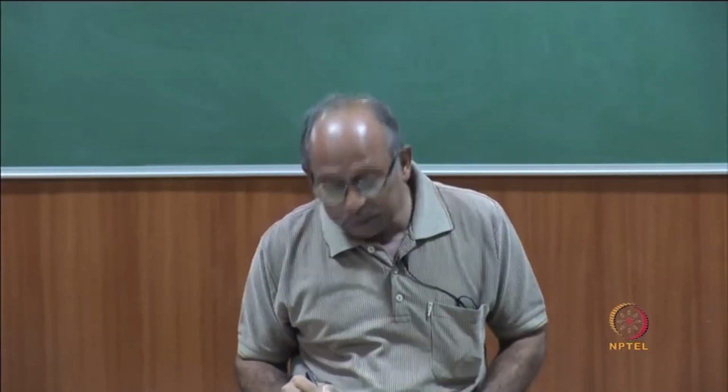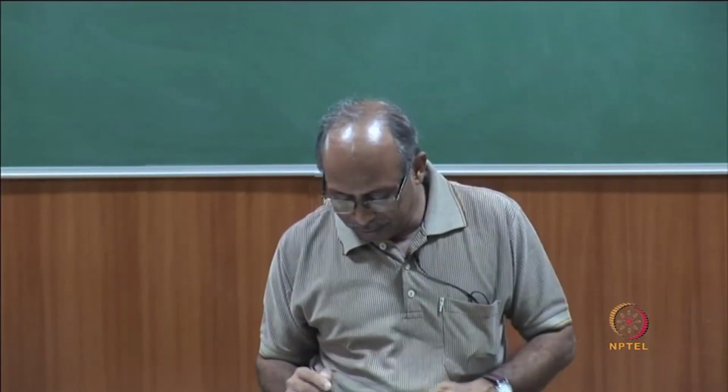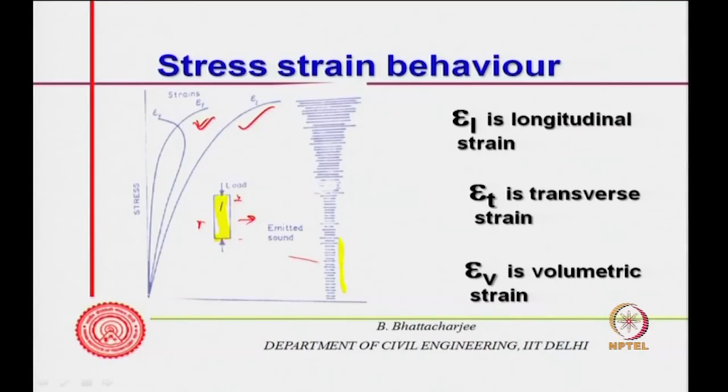So, that is actually acoustic emission. In a systematic manner one can trace this. As I increase the load, initially the emitted sound is very little, and then it goes on increasing, and the emitted sound becomes more as loading progresses. In other words, permanent deformations and non-linearity are related to a lot of cracking, and this is confirmed by ultrasonic pulse velocity also.